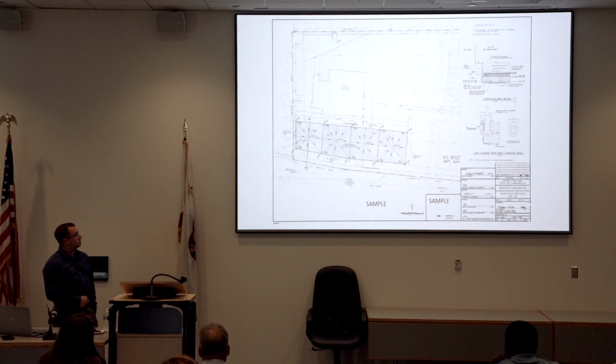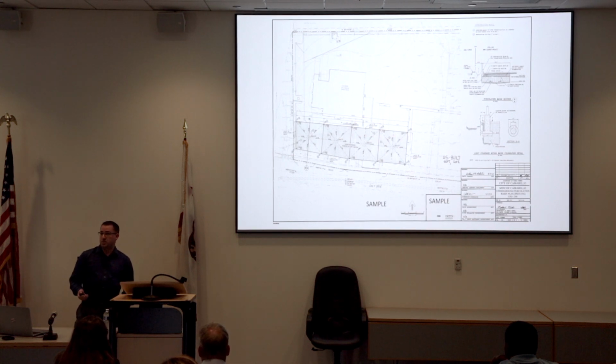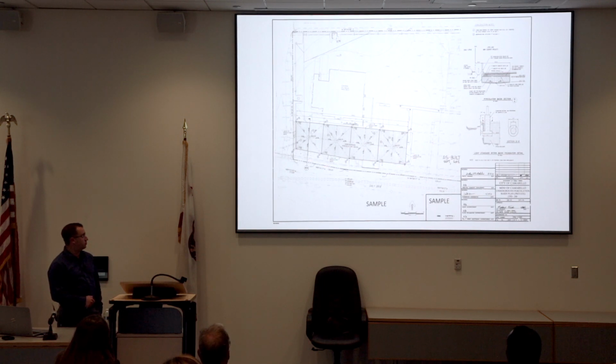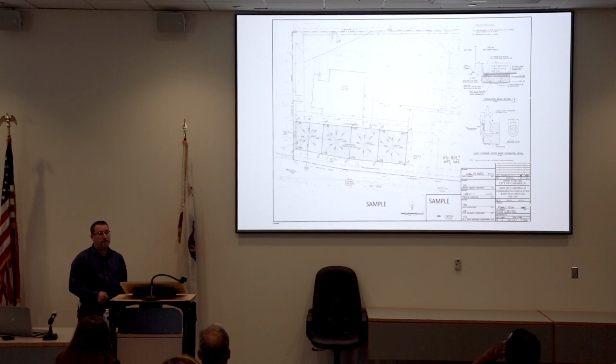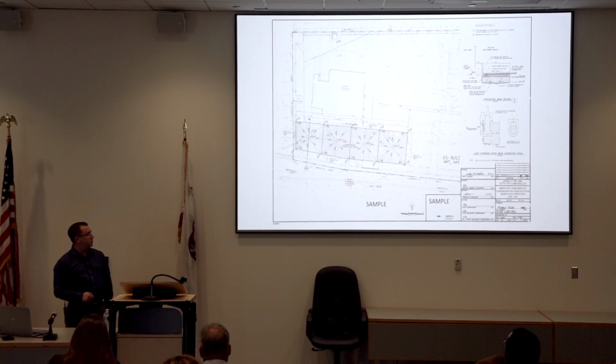So they developed this, basically a bioinfiltration, and David had mentioned before lunch that he had not seen one, and in theory, this is exactly what this is, and I'll explain a little bit more about it. Out here in this landscape area, there is a bioswale that all of the rainwater from the surface of the dealership runs off into, through these curb inlets that I'll show you pictures of too. They run off into the swale, and then they go into a pipe.